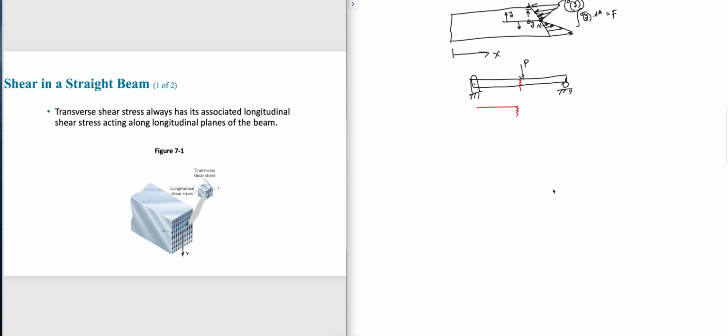And then it breaks, right? It breaks like that at some section, isn't it? Slashing off like that? That means it's becoming two parts. Isn't it acting as if we are taking a knife and slicing it off? That means isn't it acting as if there is a shear force? Because we made a cut, we have to draw equal and opposite shear force, going down on the left side, going up on the other.